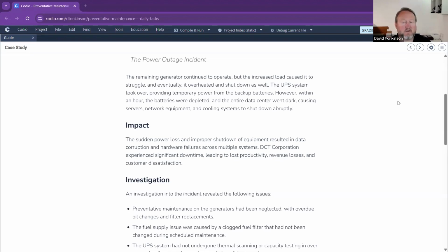Yeah, how much do these things cost to actually do? How much does it cost to change an oil filter? Oil filters for diesel generators of this sort of size are $20, $30, $40. Changing an oil filter on these things, because they're always changed regularly, is quite easy. It's not like climbing into the engine of a car. They're pretty much a stick-out-the-side job, aren't they? Probably takes 20 minutes, 30 minutes. Couple of rags, you'll be all right. So essentially, they're losing that generator because they have not performed the simple maintenance tasks that don't take very long. It doesn't cost them loads of money, but it costs them money now, doesn't it?